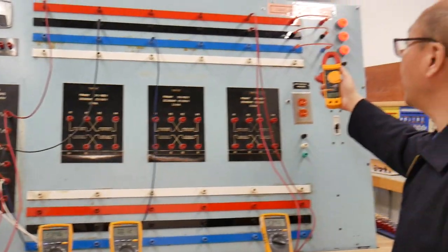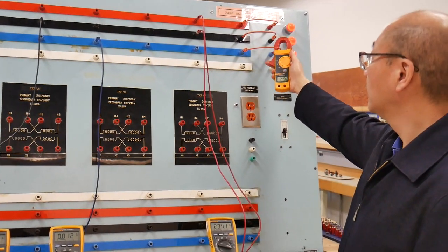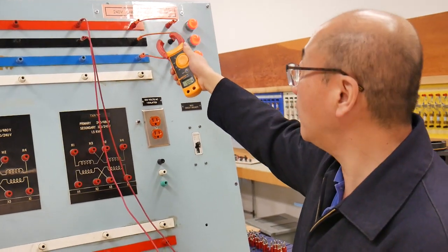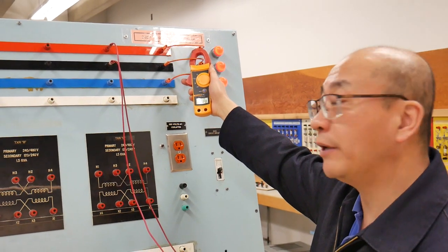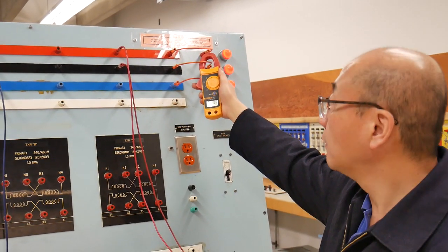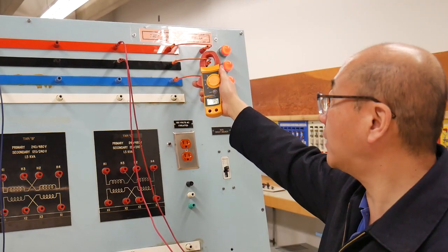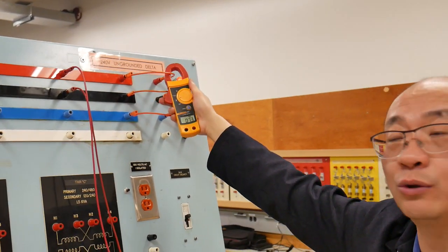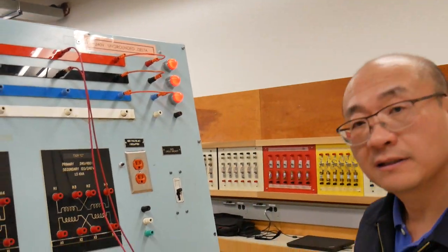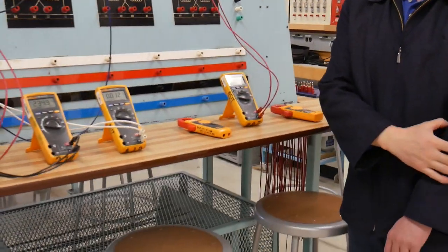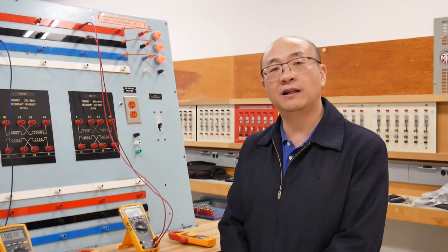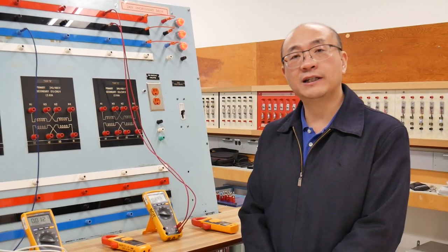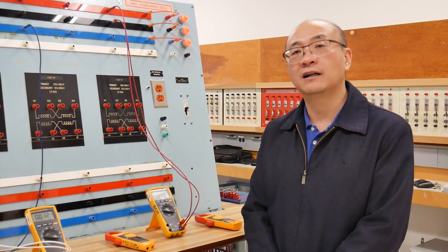So measure again for the three line currents. Line C 7.3, equal to the phase current. Line B 12.8, the vector subtraction of two phase currents. And line A is 7.3 amps, equal to the phase current. So in this lab we discussed open line and open load situations in a three-phase delta load. If you have any questions, you can connect with us online or send us an email.